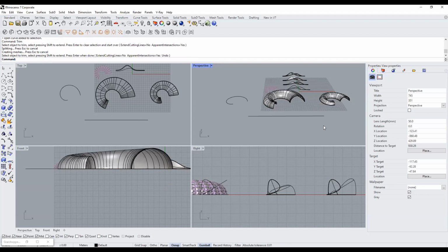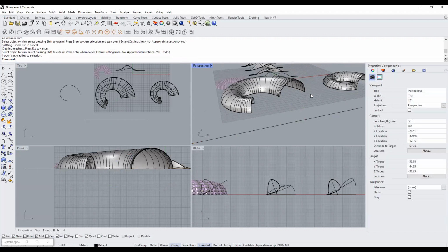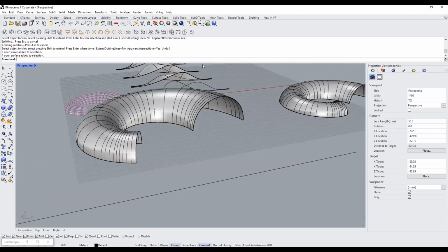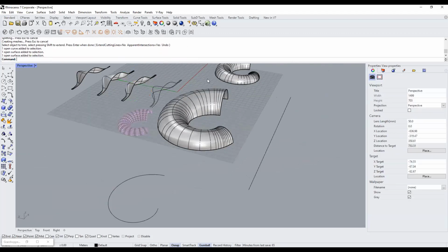That's it. So you do spiral to have the curve, and then you do pipe to get the piped object. It will be a poly surface, explode it, and finally trim below the ground level. So you have like 4 steps in achieving the shape. Try to do this. If this is confusing to you, just try a different shape. Doesn't matter. All we need is a simple surface.